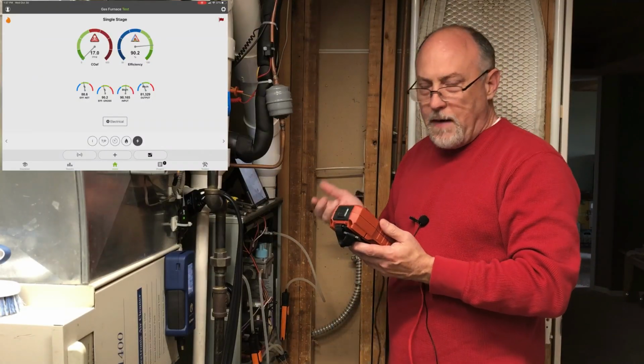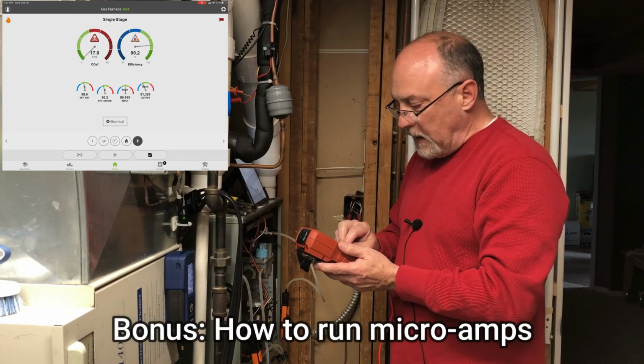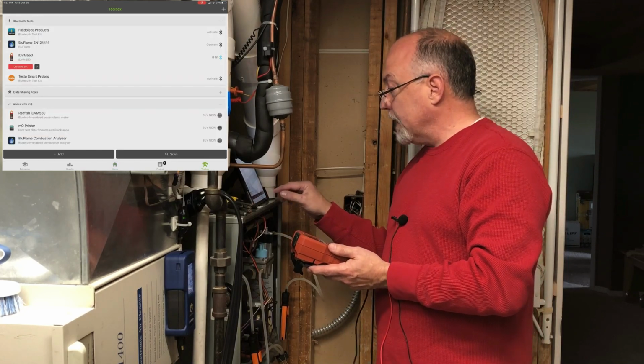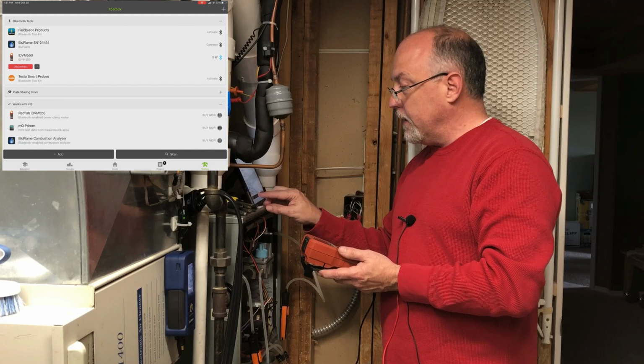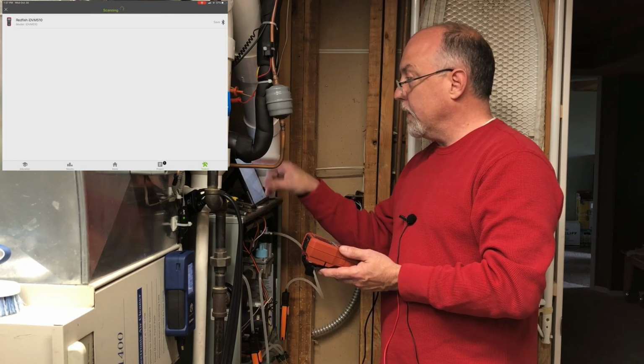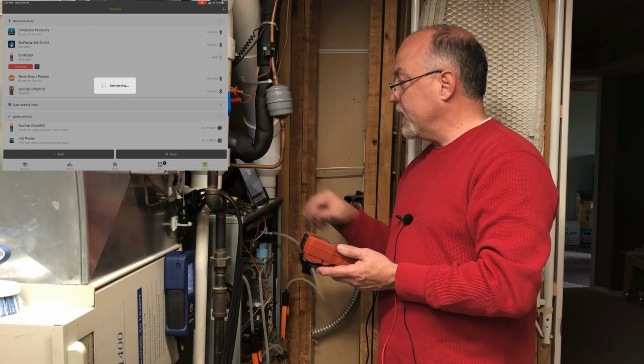All right, so to measure microamps, you do have to have the Redfish IDVM 510, and this will allow us to capture that. So I'm going to go ahead and turn the meter on. I have not put this in my toolbox. We made this really cool add button on here, so I can add a meter in quickly rather than scan for it. So I'm just going to add 510, and it'll pick it up right away. I'll just hit save, go back, and connect to it.